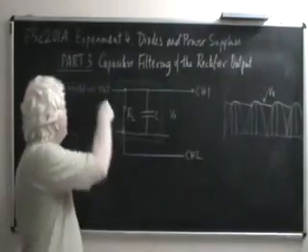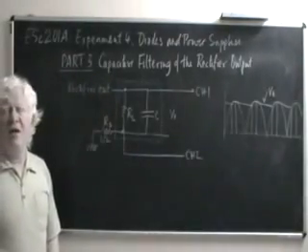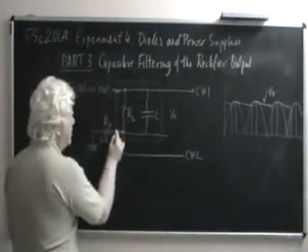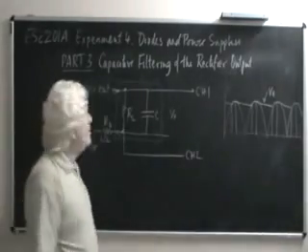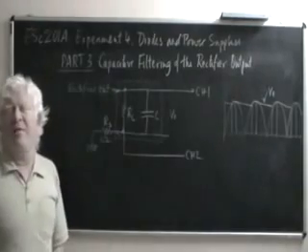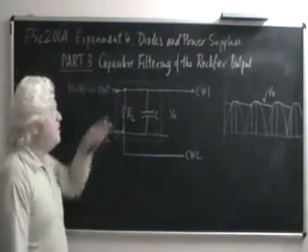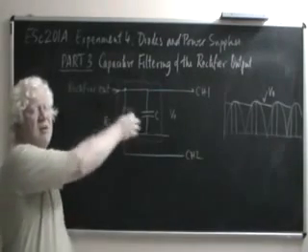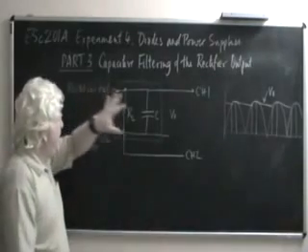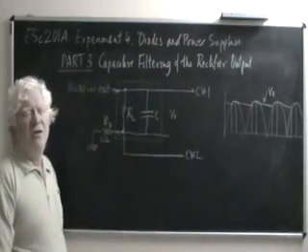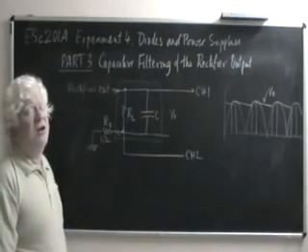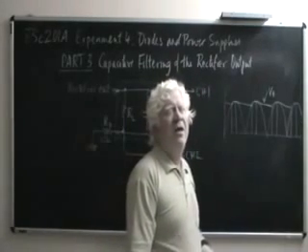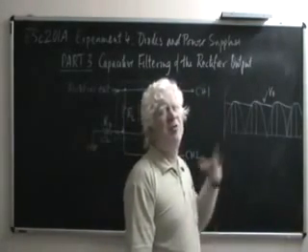So it's only when the diode is forward biased that it can conduct current. And if it is the diode current that's coming in here, it is the diode current that's going out here. The resistor itself will carry current for a longer period of time, but that current is being sourced by the capacitor, not to be measured through RS, because RS is outside the resistor capacitor pair. So this pair consisting of resistor and capacitor only allows a current to flow in for these short intervals of time, and during these short intervals of time a current will flow that is approximately proportional to the voltage.